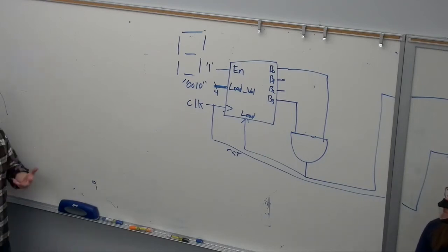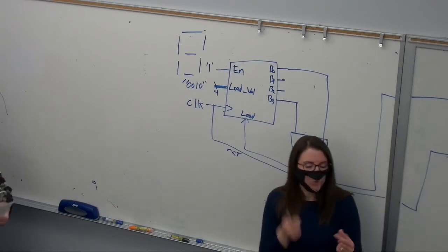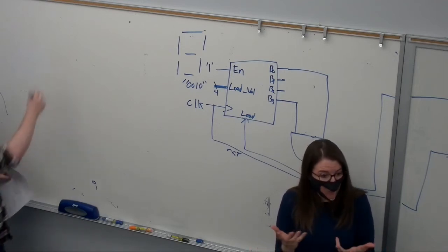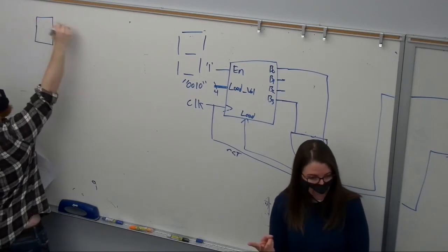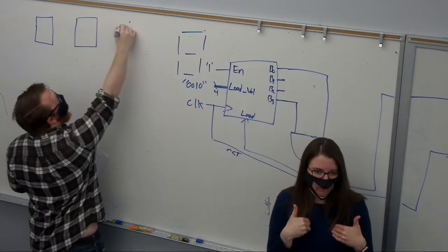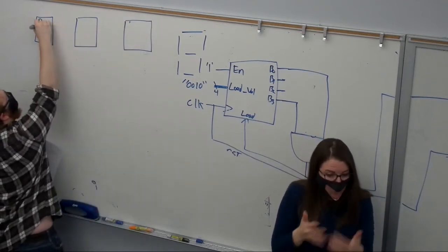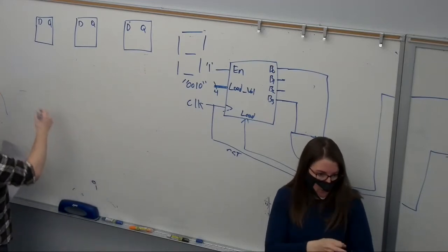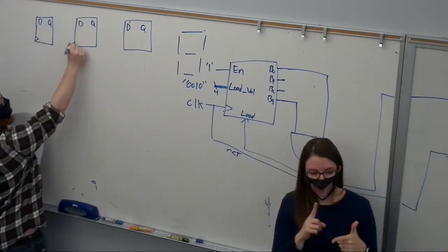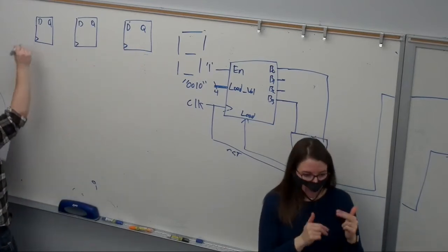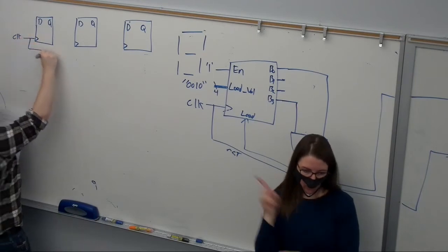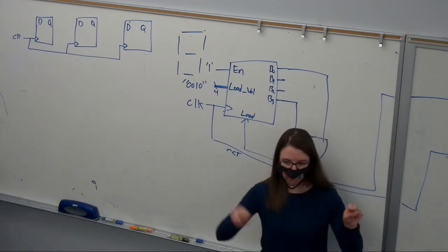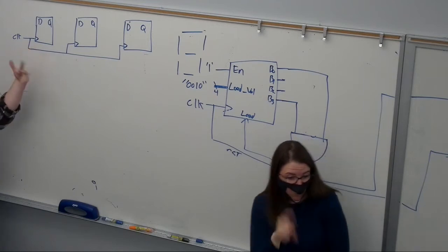Okay. So the first thing that we do is we remember that we're building these counters out of flip-flops, right? And what's nice to use is when we're building these D flip-flops, they have really the easiest use case, right? Where whatever happens at D gets put on the Q at the rising edge of the clock. And we're going to build this one synchronous. Right, synchronous clock. And a simple test question, maybe I draw a circuit like this and ask, here's a counter, is this synchronous or asynchronous counting?